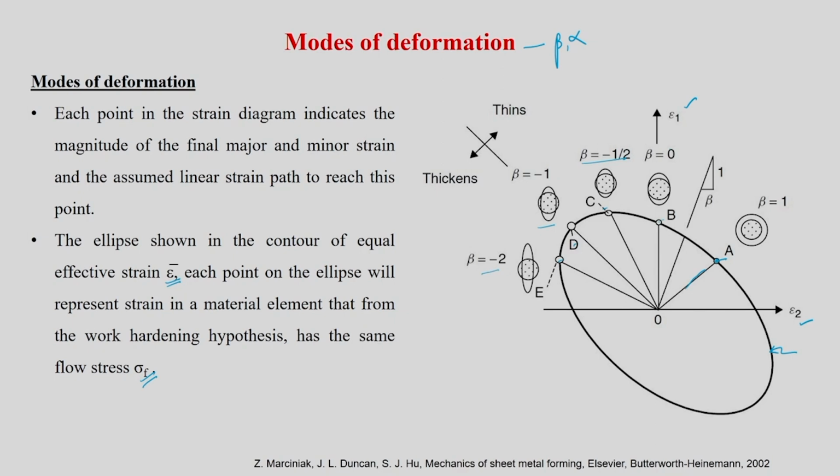And you can also see how these circles are going to get deformed. So, here the circle will become a larger circle, so that you get beta equal to 1, right. So, this dimension d0 is known to you, and the new dimensions d1 and d2 are both the same. So, you can calculate your epsilon 1 and 2 from the previous formula, and you will get the strains to be the same, that is why beta is equal to 1.